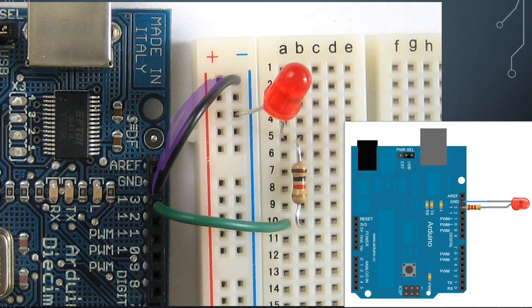Otherwise, the power is going through the board from the pins, so you typically don't need to connect that. Okay, so we have our black wire connecting us from ground, just like here in our schematic, and that's going into our LED. Now, you'll see this whole track here, this whole column is all grounded. These are all connected in this direction that I have just ran across here with my purple highlighter. So we can stick this LED into any of these pins on the breadboard and have it grounded. So we've just chosen this one.